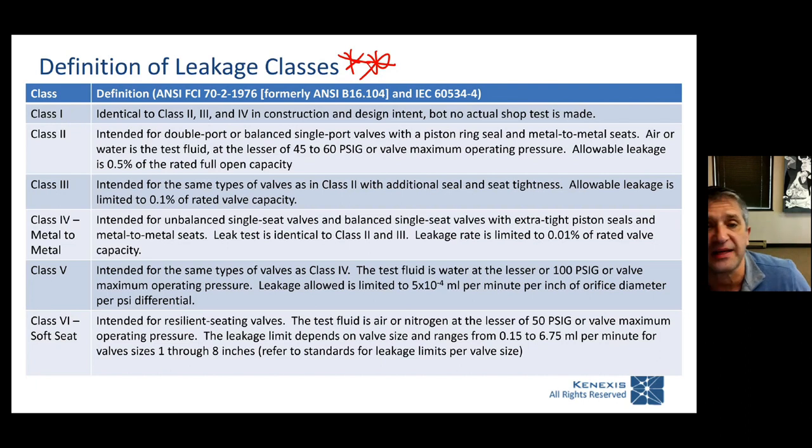Because when you define the leakage class, this ANSI standard and the IEC standard that talk about these leakage classes are going to give you a pretty airtight description of how the valves need to be built and what the maximum leakage criteria is for those valves in order to qualify for the leakage requirement.